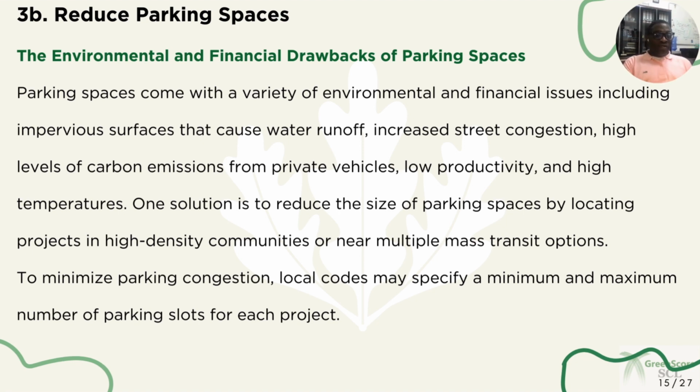increased congestion on the street, high level of carbon emissions from private vehicles, resulting in low productivity and high temperature in the communities. So one of the solutions also is to reduce the size of parking spaces in projects by locating projects in high density communities or near multiple transit options. So this is another strategy to discourage the use of private vehicles and promote the use of public transportation.